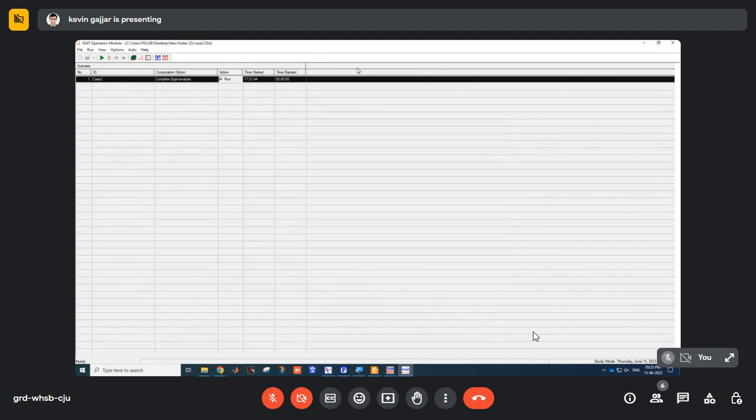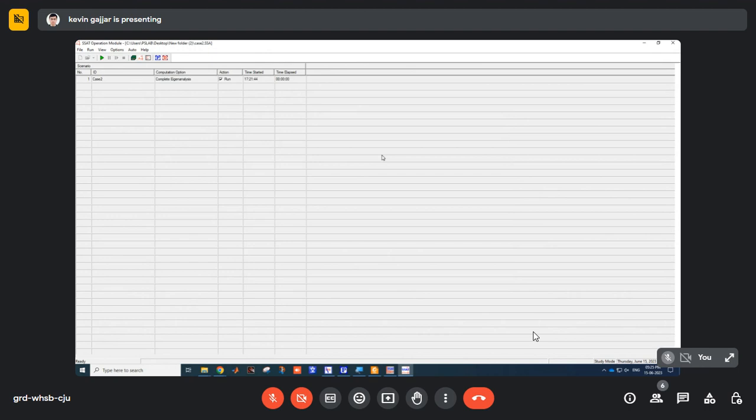It will give all the modes within that range only. Is this what we call selective eigen? Selective eigenvalue analysis, correct. This is what we call selective eigenvalue analysis, identification of a mode around a frequency or within a frequency, and we can also perform that. That is very useful when we have a very big system, so it becomes very easy to track. And it has all the functionality to get the participation factor, the mode shape, to analyze the system and all.